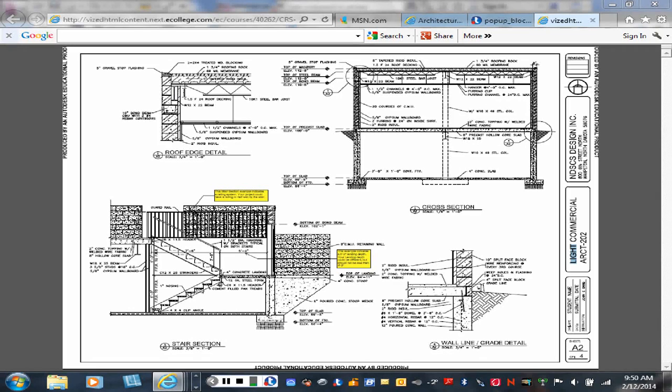So at this point, we'll assume that that height's going to be roughly 2.5 inches above the steel beam. The steel beam then, between our bar joists, we're going to try to keep those at roughly a 12-inch depth of a steel beam. And we'll talk more about that later. But I think, again, as long as we don't get over, I'll say, a 30-foot span, we should be able to get by with a W12 by, it could be a W12 by 20 or it could be a W12 by 60. It just is going to be in that 12 range.